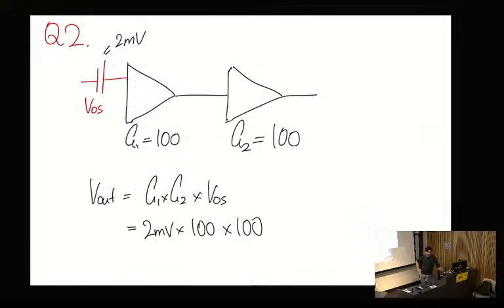How do you measure it? Yep. So to those online, let me know if there's any questions online. But to those online, the question is about how we distinguish really small signals from the offset and the noise floor as well, when they're all very small. It's a bit of a cop-out, but we use low noise amplifiers. We have amplifiers which are called low noise amplifiers for those specific purposes.